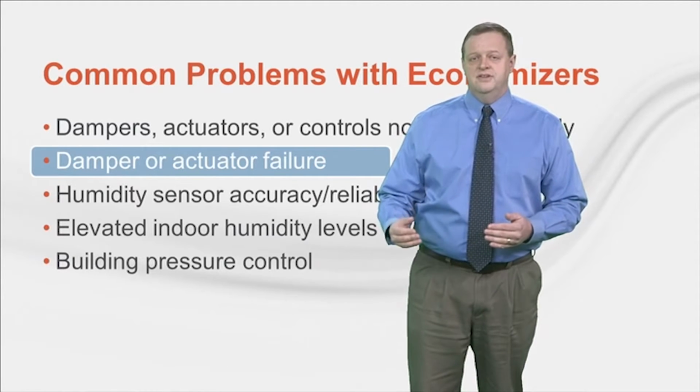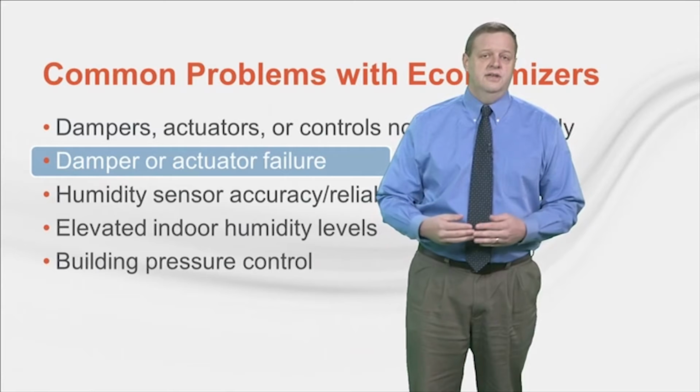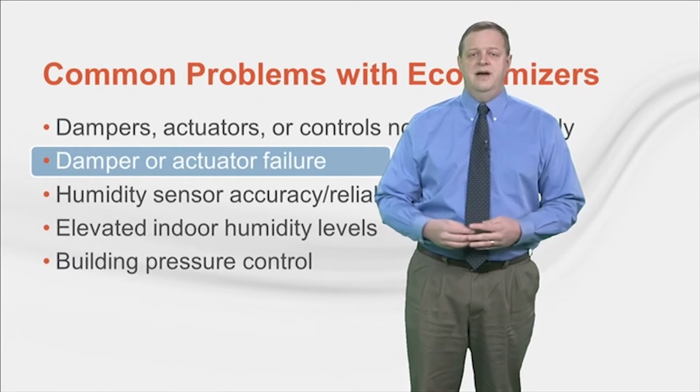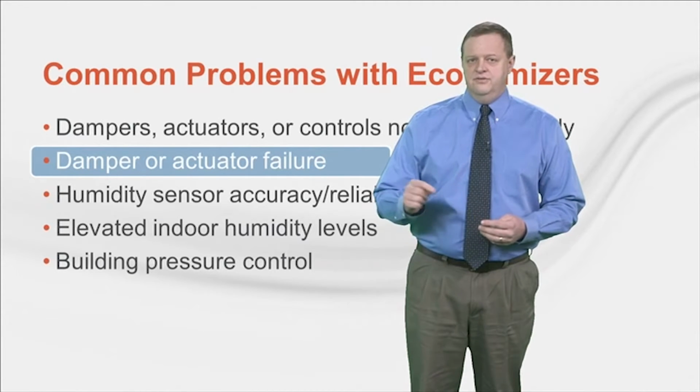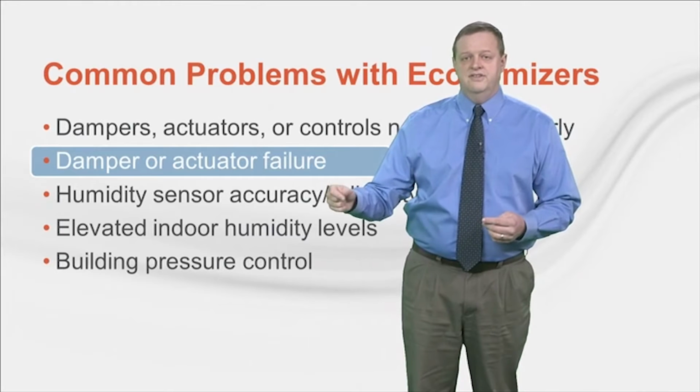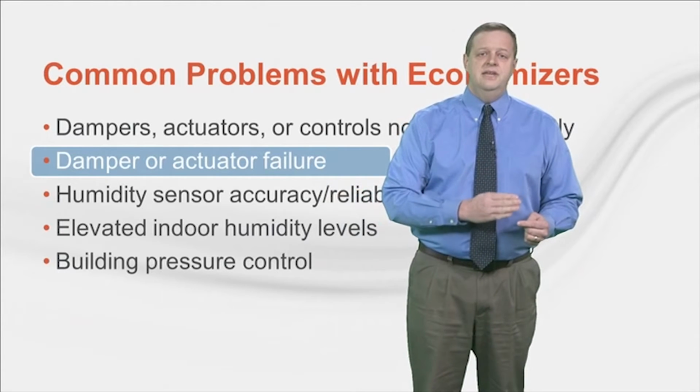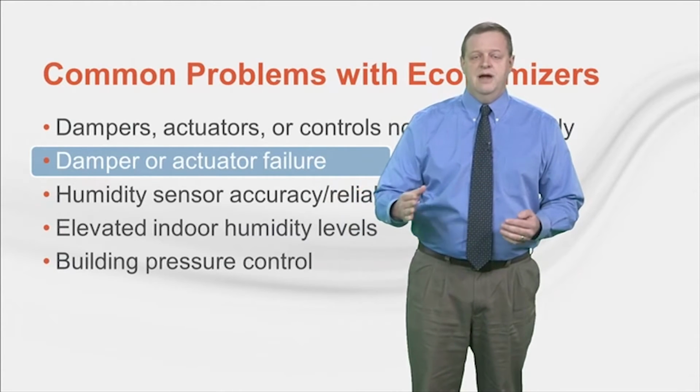But if you had multiple units on the roof, you could really do them all concurrently, which gives each unit time to respond to each test. That is, you would move from unit to unit to change the control settings, and then start back at the beginning to confirm that each one had the proper response.